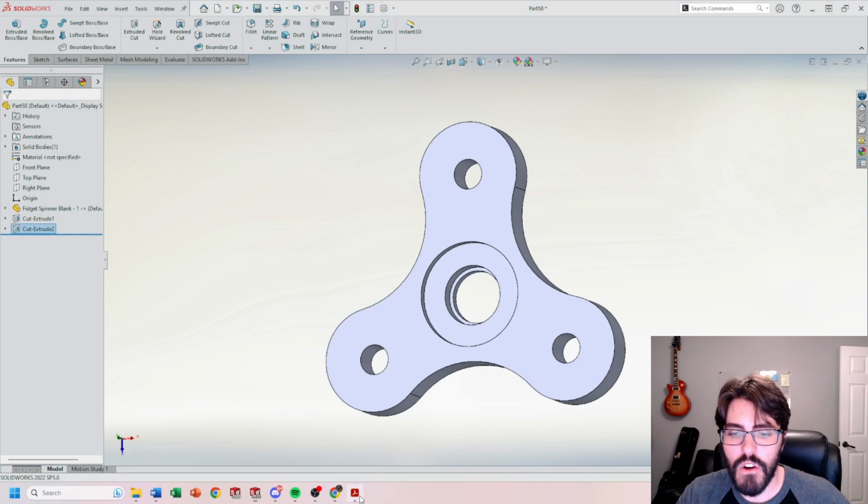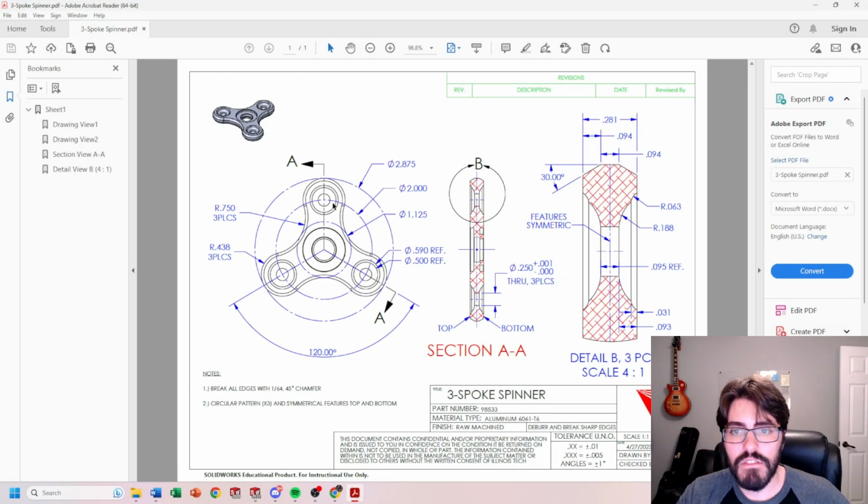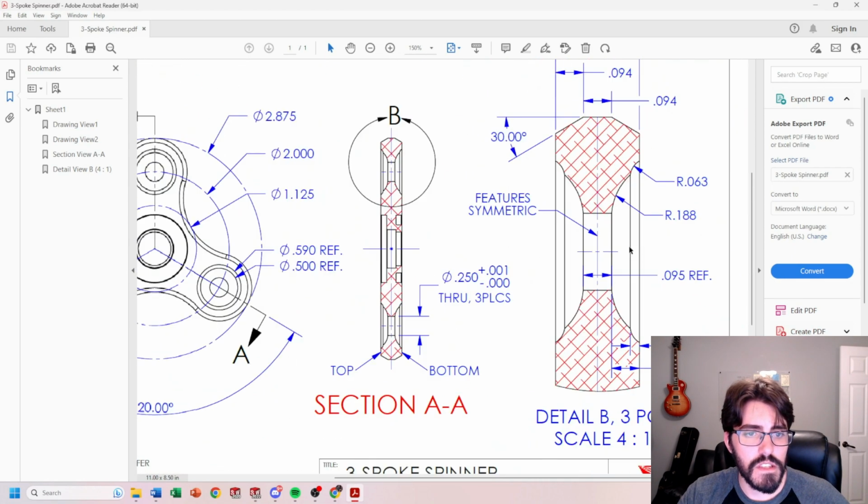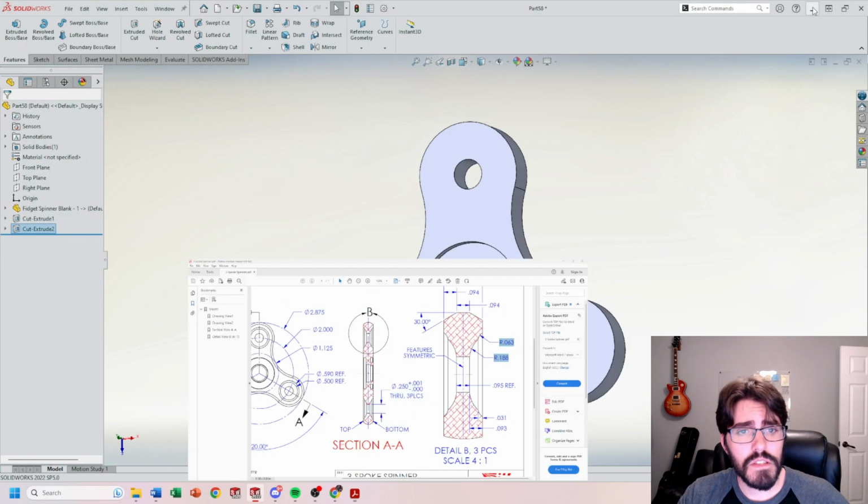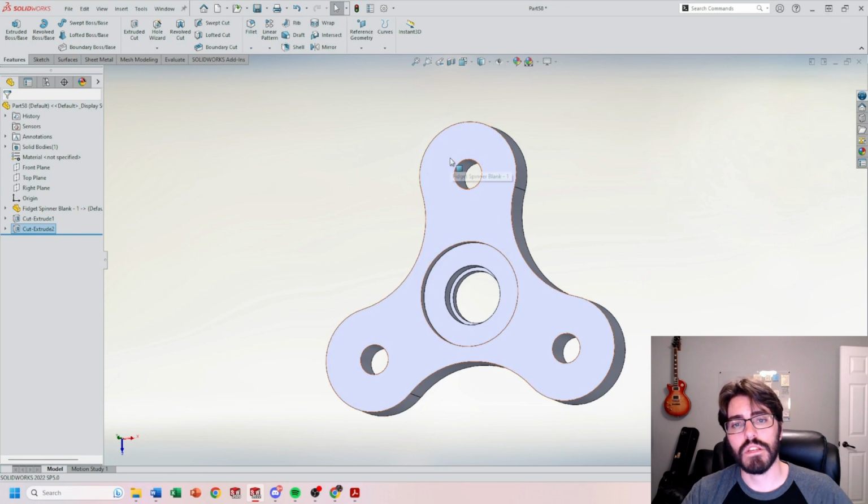If we hop back over here to the blueprint, I have some of these reveals that are going to include a fillet as well as a ball mill, or an edge break, on the top edge of that ball mill. So it's almost like a two-tiered feature, and you can see that here. We have the top view, we have the cross section, and if we zoom in here, this is the detail view of that cross section. We have some radii that we have to consider, and then the depths of where they're going to be placed. So let's start working with some of those.